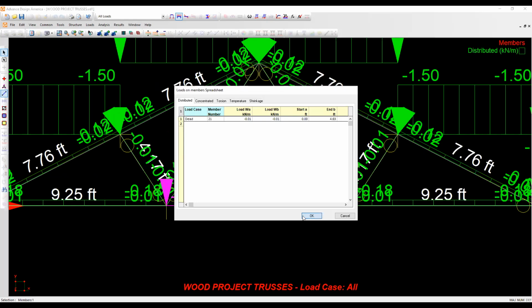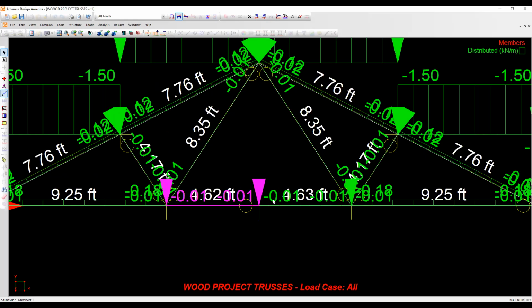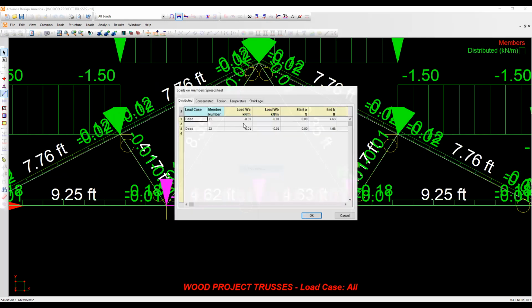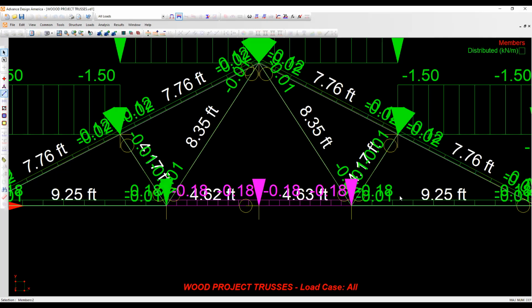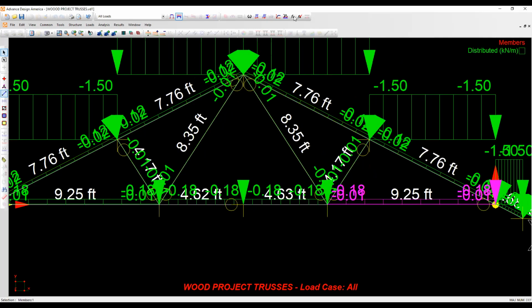All right. Okay. So let's fix this. See, guys, what I'm saying is that if we want to get the same results, we have to have exactly the same loading, exactly the same member lengths, you know what I mean? That right there is going to start changing things. In other words, you're putting more load on the bottom chord, you're going to have a higher axial force in your web member, so it's going to get closer to the other one. You understand? If you rerun your analysis now, okay.